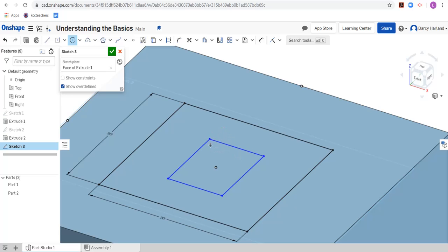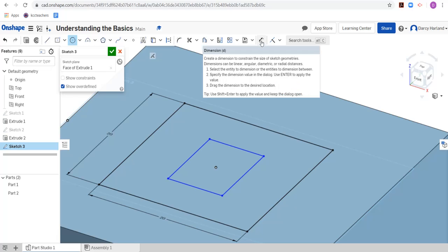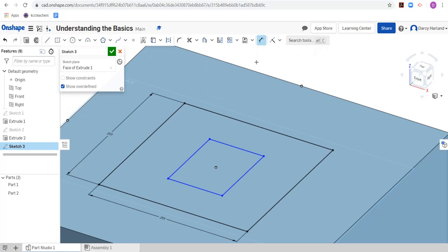Okay, what I can actually do is go to my measuring tool here. This one at the top here, it's near the very far right of the 2D tools here. Dimension tool. You can hit D on your keypad as the fast way to get to it as well. This is the tool that's going to measure points for me. So I can essentially click on 2 points and it will tell me how far it is between those 2 points. So I'm going to use that to actually measure this line. I'm going to go this corner to this corner and it's going to show me how long it wants to be. So it wants me to simply plot that measurement down onto the ground first, and then it gives me a chance to edit it.